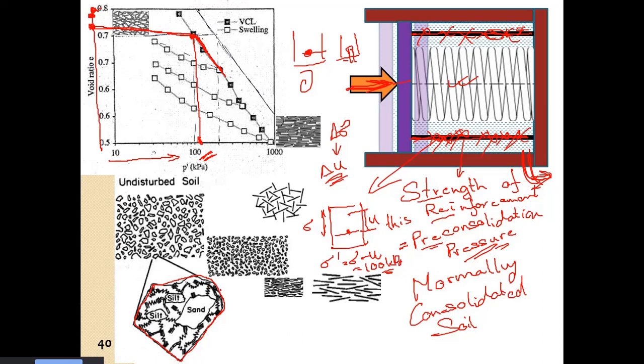Suppose we say, as soon as we reach the pre-consolidation pressure, this structure will start rearranging itself. It will break, so it is no longer in an equilibrium state. But it will not totally collapse. You do not think of it as a card house where you just give some displacement and the entire card house will collapse. It is not like that.